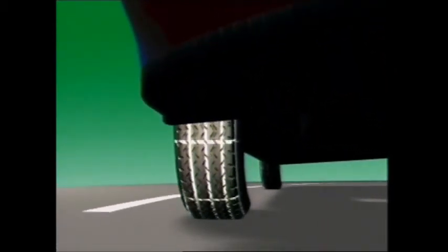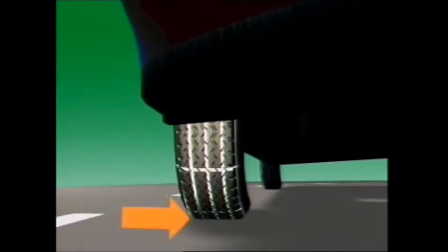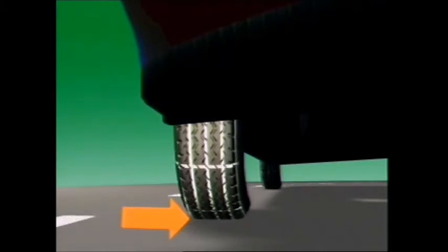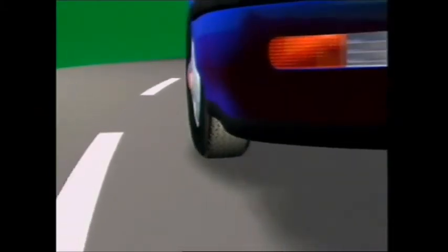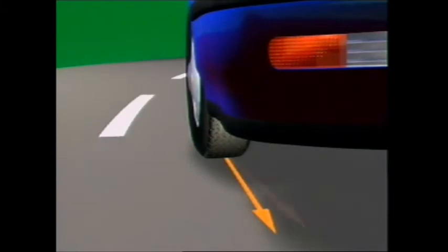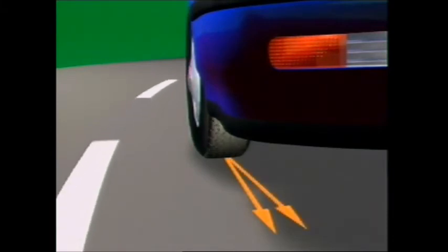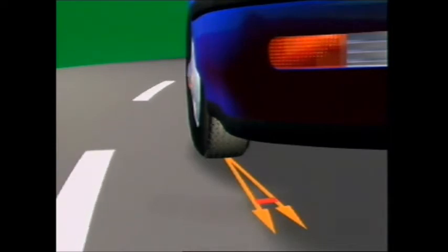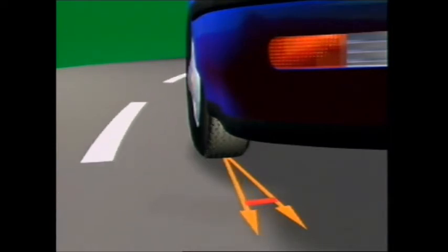Then, since the tyre's construction makes it elastic, it exerts a force called cornering force, which acts between the tread and the road surface. It pulls the distorted rubber back to its normal position. The tyre's sideways distortion makes the vehicle follow a path at an angle to the direction the road wheel is pointing. This is called the slip angle. As cornering force increases, so does slip angle.